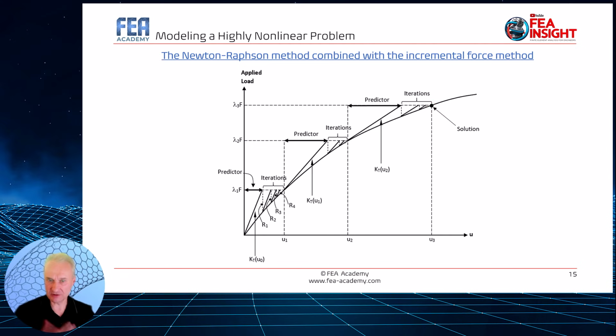So the incremental process continues until the residual parameters are within a tolerance defined by the FEA analyst. Note that the load increments do not have to be uniform, and the critical parts typically require a smaller increment size.